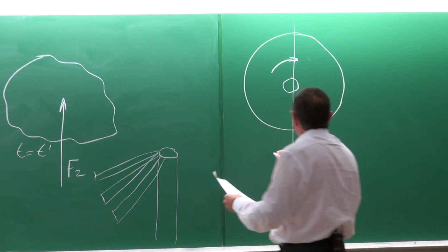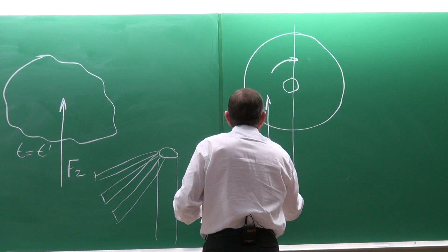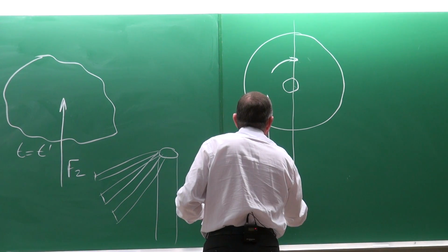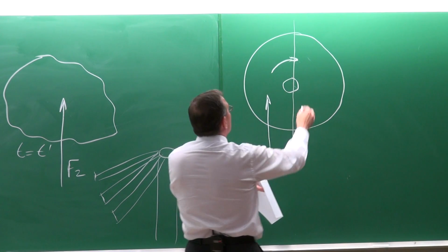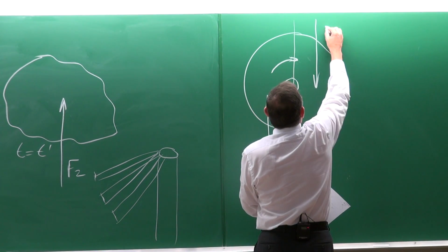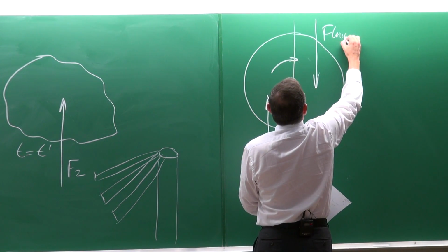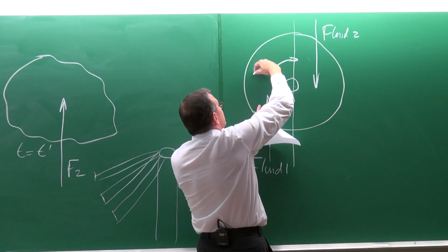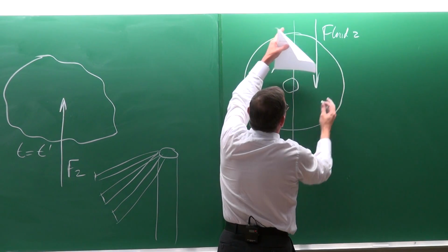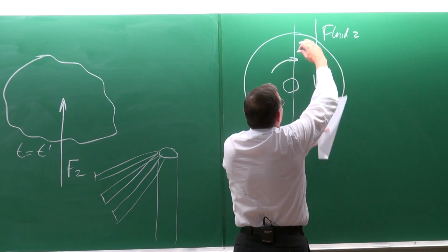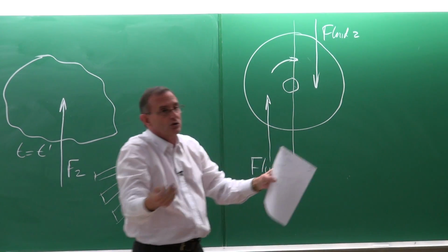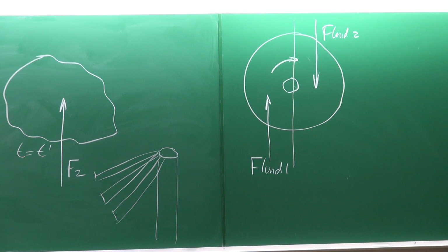Then we will have fluid 1 that would typically heat this porous media, and there will be fluid 2, and they do not mix. So here it will heat it, and the heated porous media will then go into the cold stream, and the heat transfer will occur on the cold side. So that is called the dynamic type, and this is called the static type of regenerative heat exchangers.